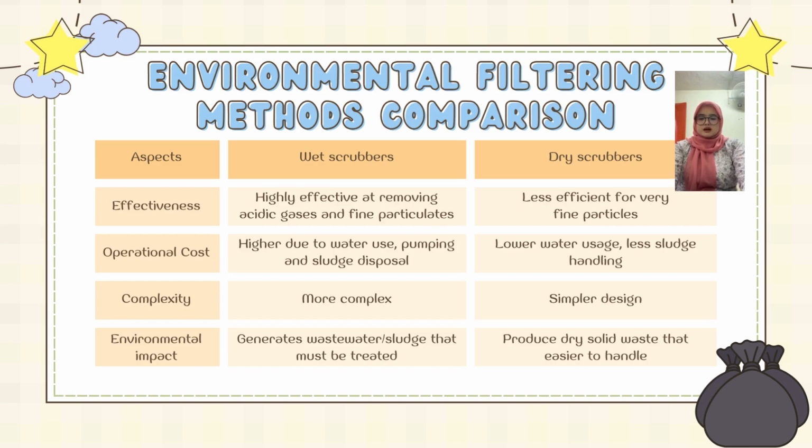Wet scrubbers are highly effective at removing acidic gases and fine particulates, but they require more water, energy, and maintenance. This makes their operational costs higher because of pumping and sludge disposal.